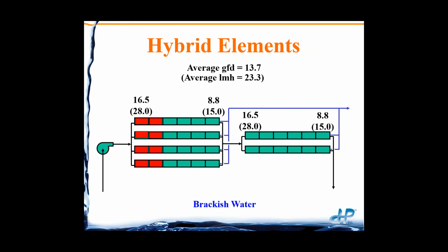So here just an illustration that we've put low permeability, high salt rejection membranes in the first two positions in this case, and then the rest of the membrane elements are higher water permeability, lower salt rejection membranes. So this then forces water to go more downstream of these first two elements, so it reduces the water flux rate on the first element.